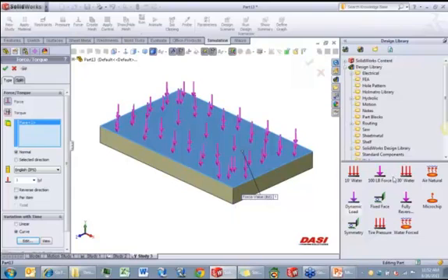So keep in mind when using this, it's not just for static studies, nonlinear studies. It's also for even thermal studies. If you want to apply natural air convection to a face, or forced water convection, or maybe a heat power, microchip heat power over to a component, you can save all those boundary conditions in here so you don't have to redefine them every time.